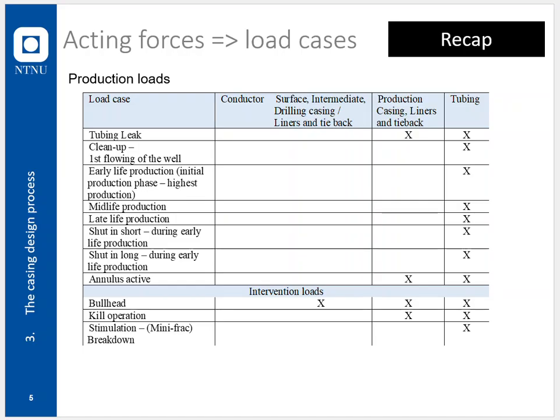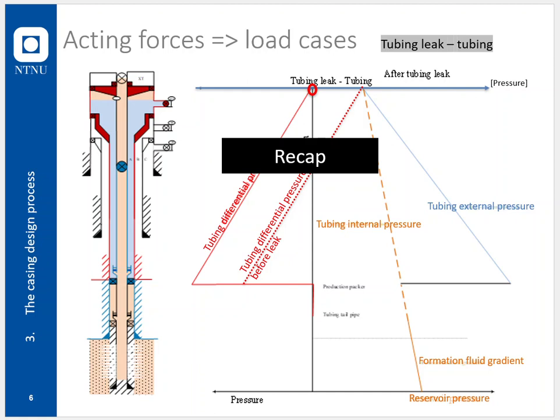and very often the ones that set the design of the casing, meaning how thick the walls of the casing need to be and its yield strength.